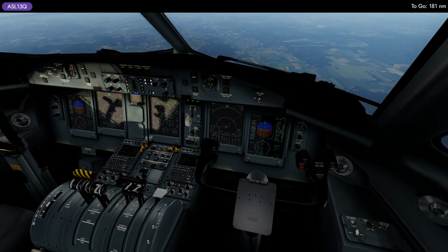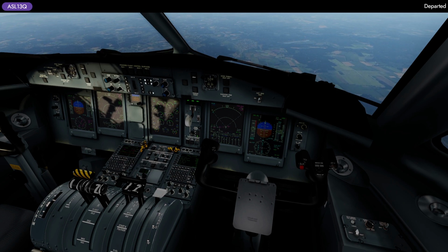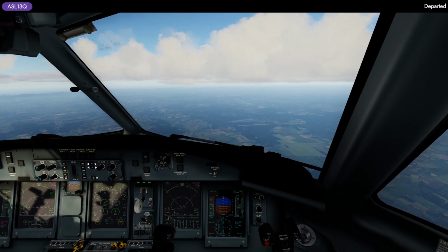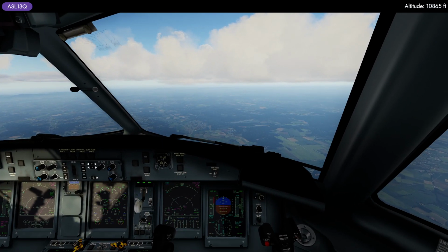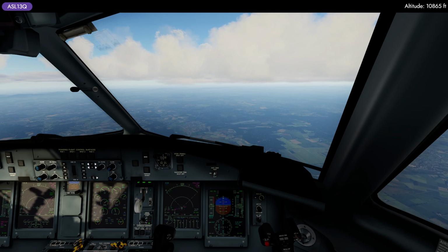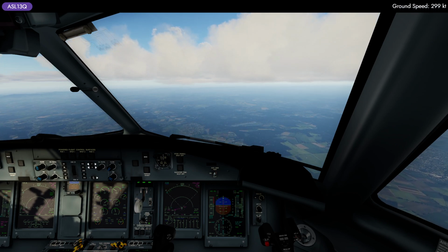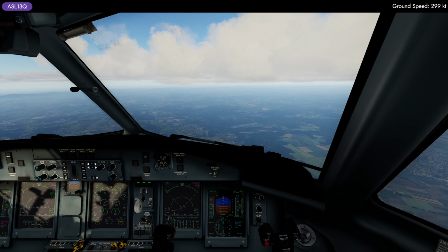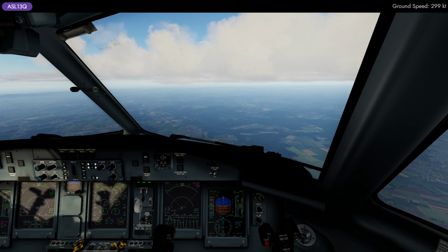116 here. One thing I didn't check, and hopefully I'm still above it, is my sector altitude. And the sector altitude is 3,300 and 2,800, depending. The limiter is the radial 222, so we should be fine.